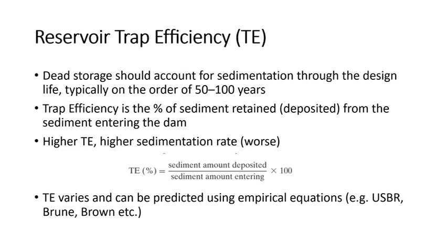Now, TE is essentially just sediment that is retained divided by the sediment that is entering the dam, in percentage. Alright, now we can estimate the trap efficiency, or TE, from empirical equations like the USBR, the Brune, the Brown, and other equations from other authors.